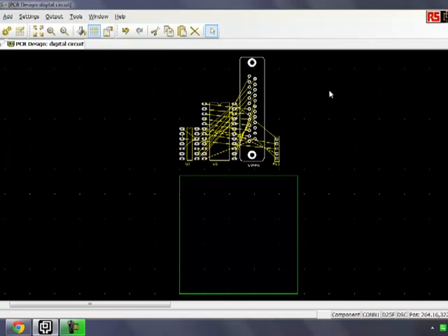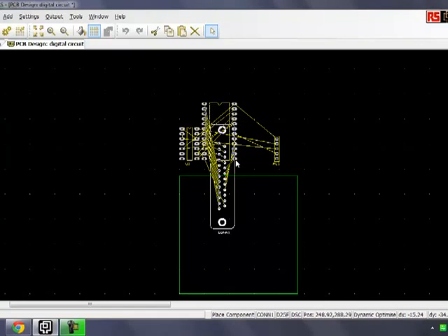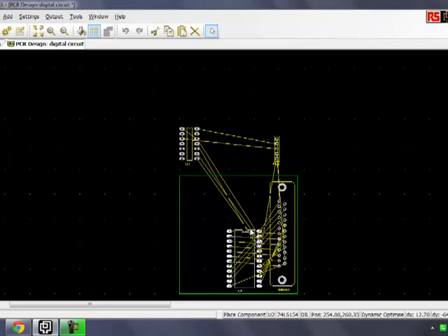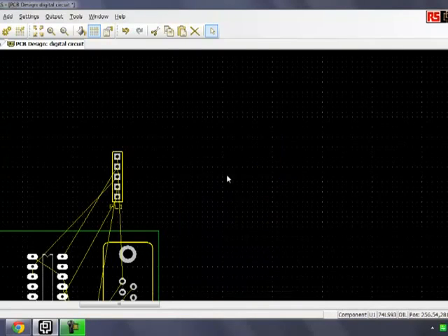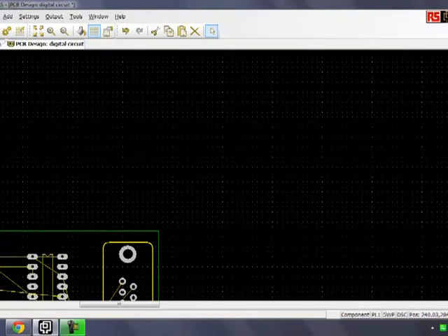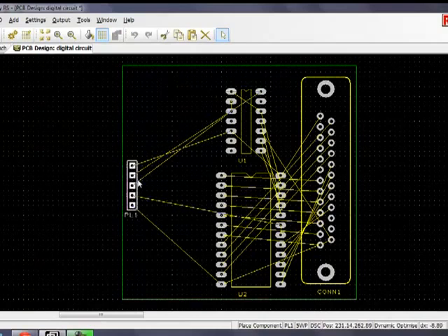So quite simply, at this stage, what I can do is pick up this connector, and you can see here that all the nets that we set up have been translated. What we can do now is bring these components down just by picking them up and dropping them. Oh, we just zoomed in on the screen, sorry there. Okay. We just press A, we remember, it's a shortcut command, it should take us to all. Here we can see the board now. I'll just move this down.